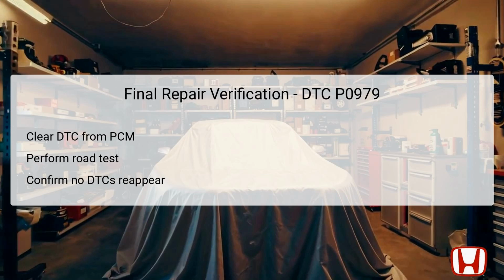After completing all necessary repairs or replacements related to DTC P0979, a final verification is crucial to ensure that the issue has been resolved. Start by clearing the DTC from the Powertrain Control Module, PCM, using the diagnostic tool. Subsequently, perform a road test under various driving conditions to monitor the vehicle's performance closely.